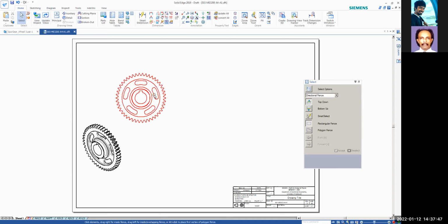Now I want what? See, I want to have a sectional view. There's no point of giving the top or the other one, because if you try to give that section view, you can see with all these gear teeth, it's going to be very difficult to understand. Don't produce any view which cannot be read very clearly and then interpreted and understood. Right? Okay, you can try.